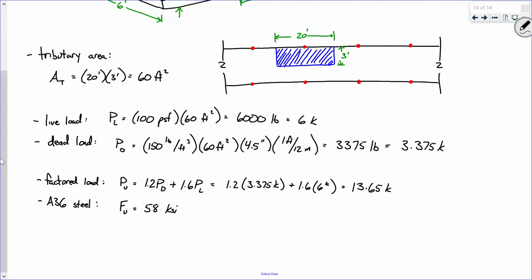Now, the steel mills were fine, because when they sell a piece of steel to a fabricator and an engineer specs out that piece of steel for a project, the steel mill was like, well, we know we're meeting the spec because we're getting 58 and more, right? The problem is that by actually getting a larger Fu than what we were speccing, the buildings weren't able to withstand as much deformation as we thought they were.